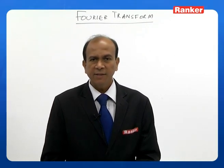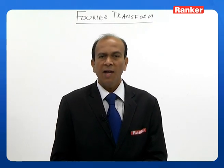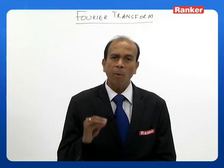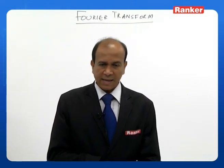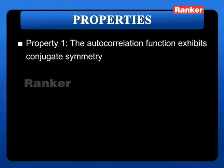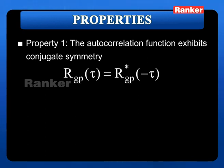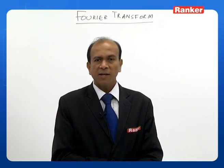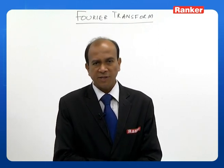So, let us see its properties. What are the different properties of an autocorrelation function of a power signal? Let us start off with the first property. Property 1 says the autocorrelation function of a periodic signal or a power signal exhibits conjugate symmetry, that is Rgp of tau will be equal to Rgp star of minus tau. Here Gp indicates it is a periodic signal. This property is similar to the property of an autocorrelation function for energy signals also.